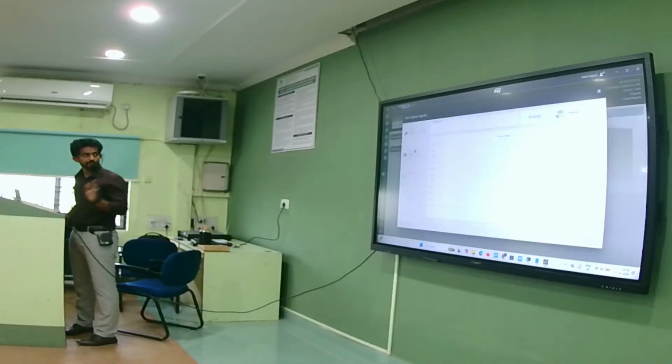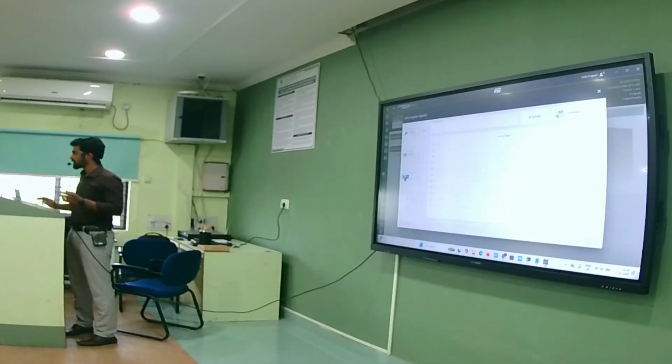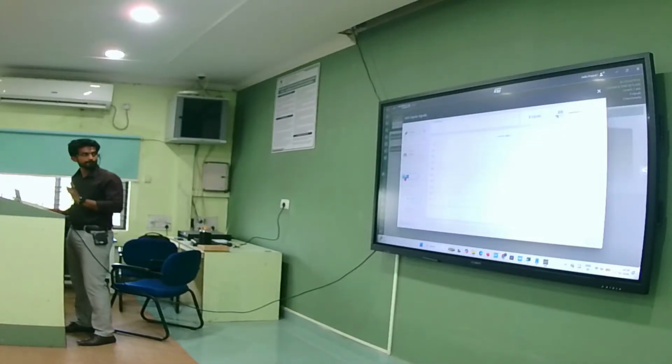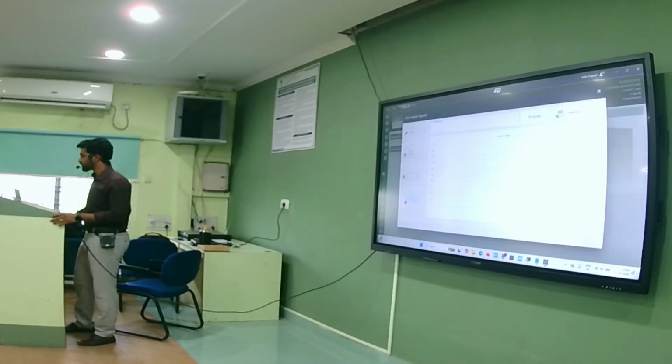And this page will appear. Here, which one will we use? My ST link is connected to COM29. Yours will be different. Here, for the baud rate, the maximum number of lines is 200. Make the maximum number of lines 200.